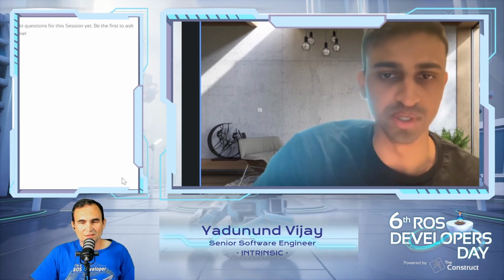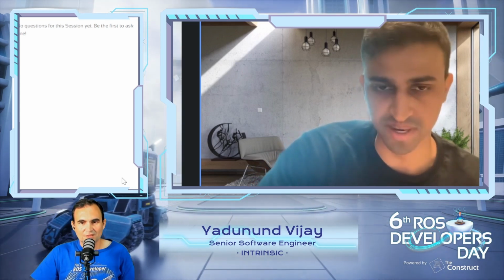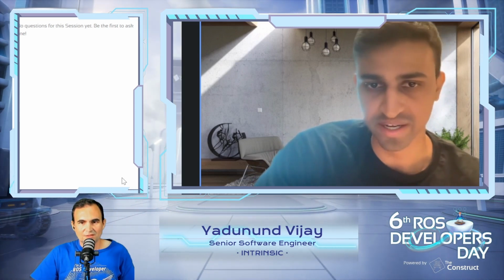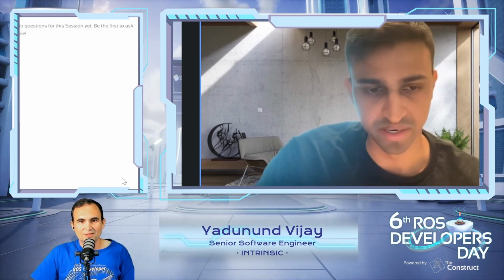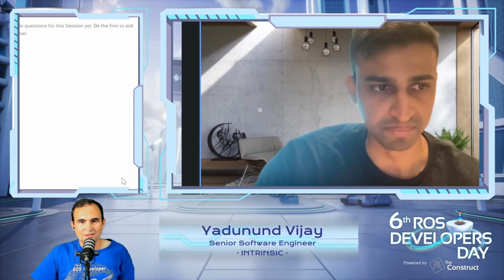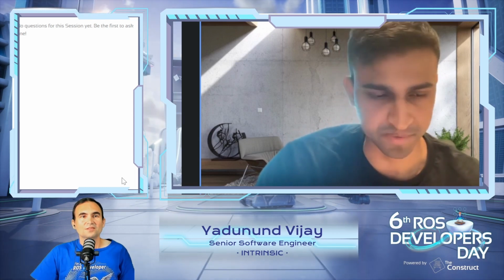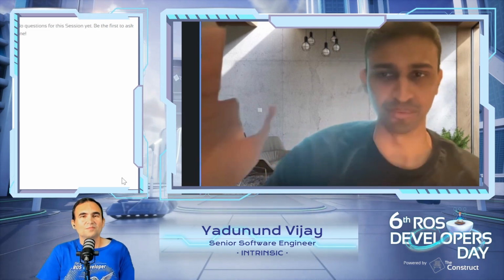You get that information back, and then the Fleet Adapter API will automatically convert that to a ROS2 message and send it to the other RMF nodes that do the traffic management. So your robot can be ROS1, ROS2, can expose REST API, WebSocket, OPC UA, EtherCAT, whatever you want. That's totally okay. You should be able to integrate any device with OpenRMF.